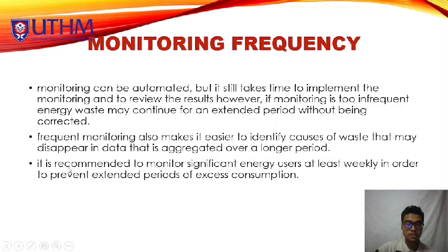Okay, next is it is recommended to monitor significant energy users at least weekly in order to prevent extended periods of excess consumption.